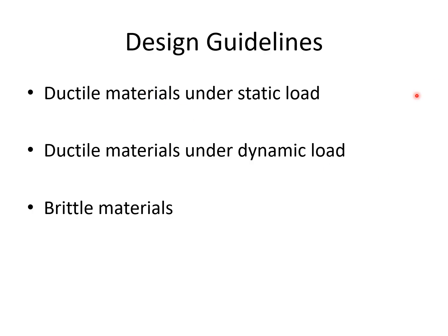Design guidelines. For ductile materials under static load, we need not consider stress concentration, because even if there are some changes in cross section or small cracks, there will be yielding near that point.